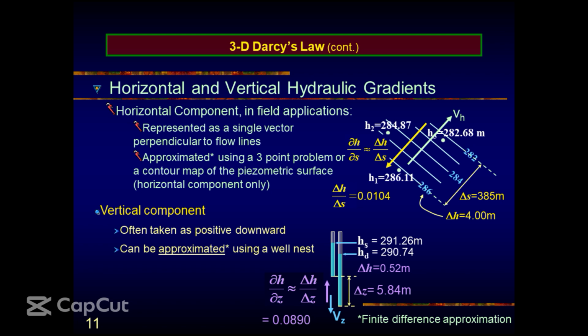Not hydraulic gradient? Gradient, right? Because we are moving towards the direction of the greatest rate of increase in the pressure head, isn't it? So this way we have gradient, del H by del S, or delta H by delta S, because we are considering a horizontal plane. That's why we are using the S. And it has to be perpendicular to the equipotential surface, meaning this angle is 90 degrees.